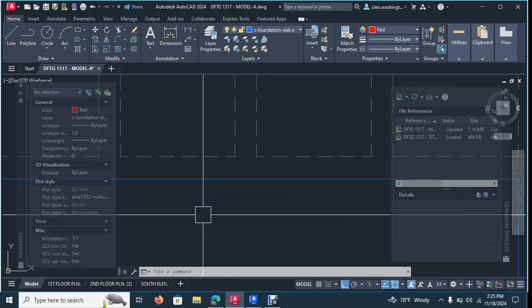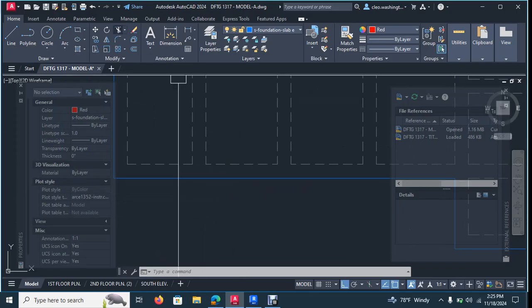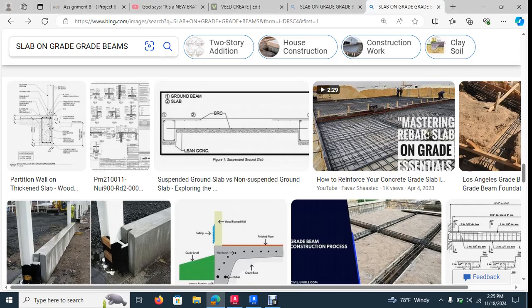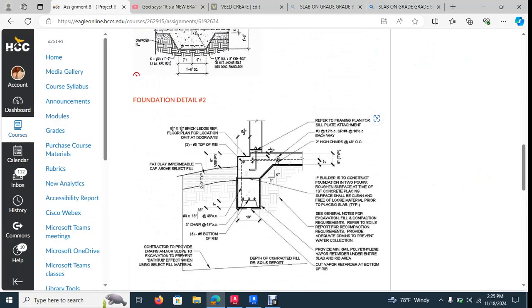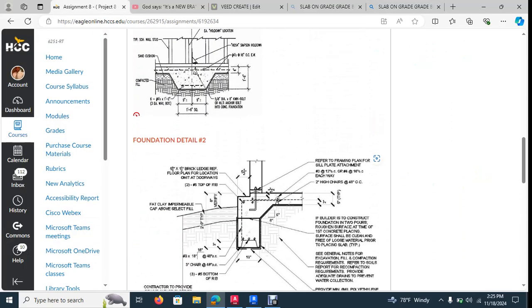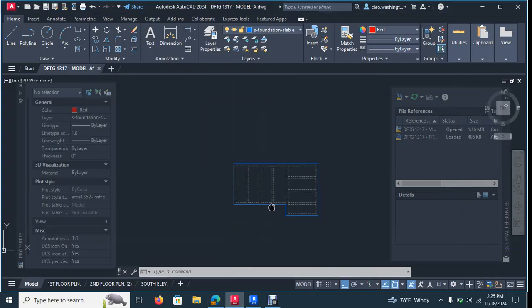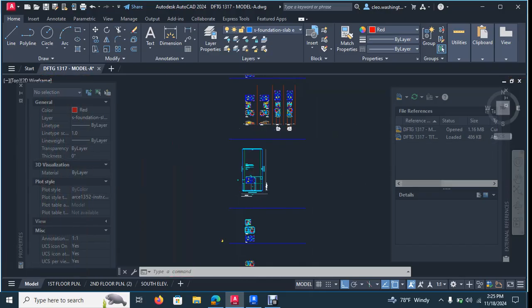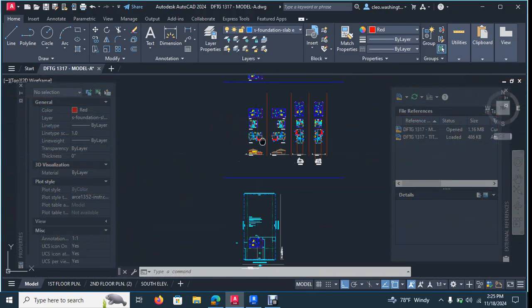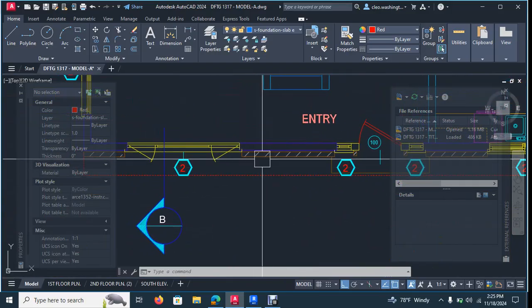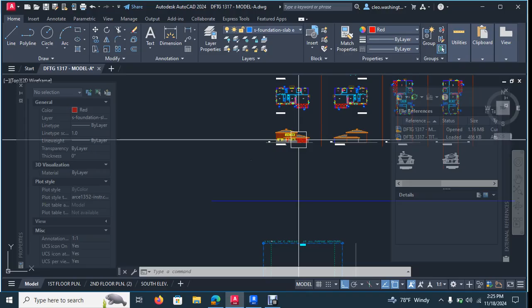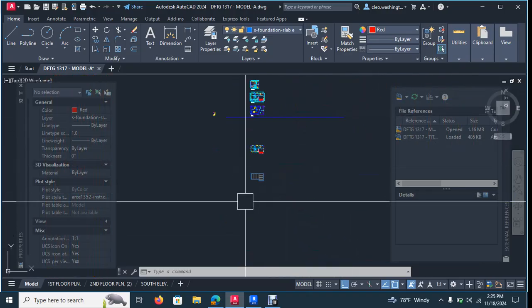Okay, now when we go back and we look at this guy right here, we have to show that brick ledge, all right? So it's 5.5 inches. So we have brick shown where on our drawing? We have brick right here on the front side, right? If you go back to the elevations, or if you just go back to the floor plan, there's brick right there and right there only. So we have to have a brick ledge on that front side.